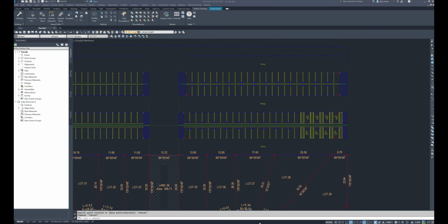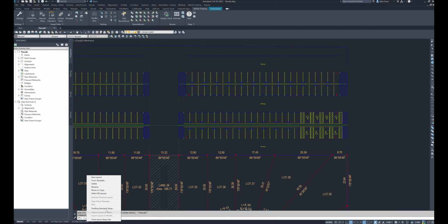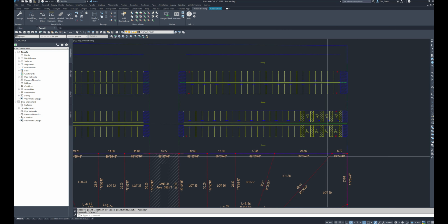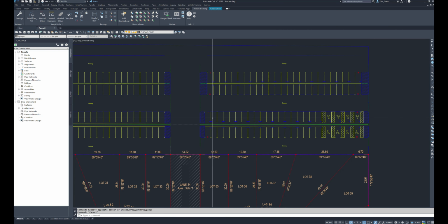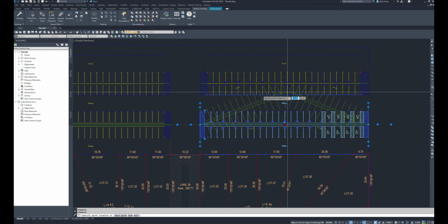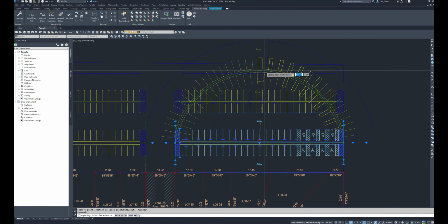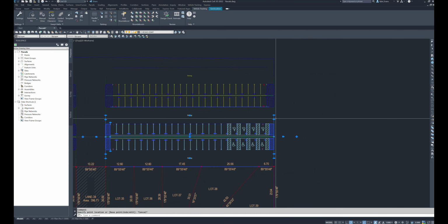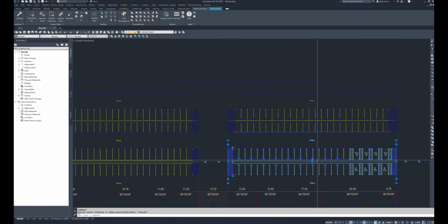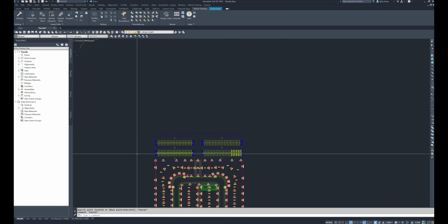So a lot of very good options. And I'm trying to, there we go, dock above status bar, so my screen stops flashing. A lot of options we can play around with. We can insert a vertex in the middle. Say we made a mistake or need to change the angle of it. The arrow will put a curve in, so we can place curved parking lots. And the grips on this side really do the same. So again, just get into the software, play around with it. This was a quick throw some very generic parking stalls in there and modify and tweak it from there.